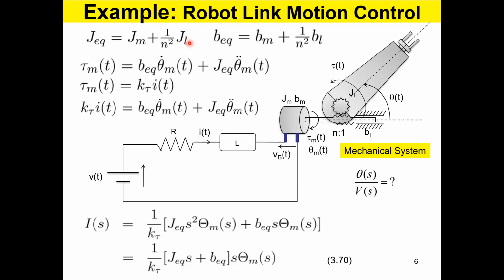and the gear is a reduction gear, maybe 100 to 1, 50 to 1, 150 to 1, that kind of speed reduction, and let's call the gear ratio N to 1, then the entire inertia of the load, as you see it from the motor side, would be JL over N squared. That you have to remember: inertia divided by N squared, if the gear is a reduction gear.